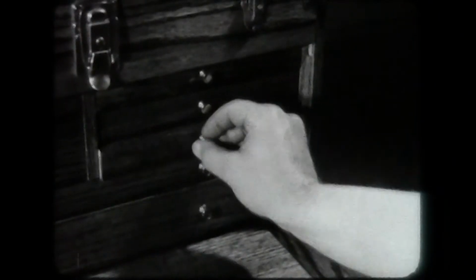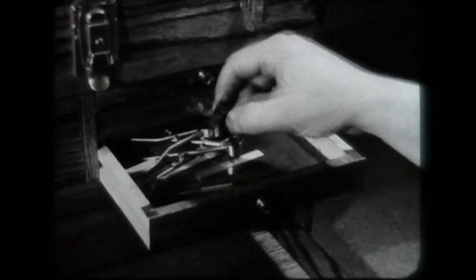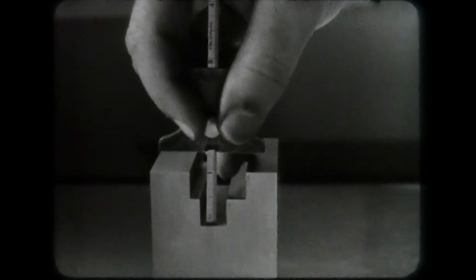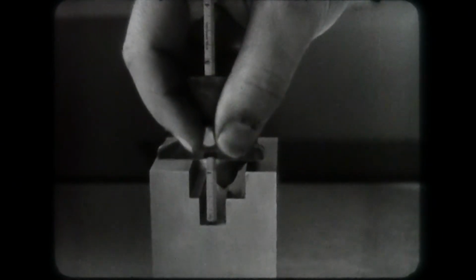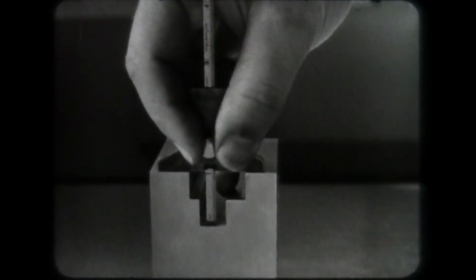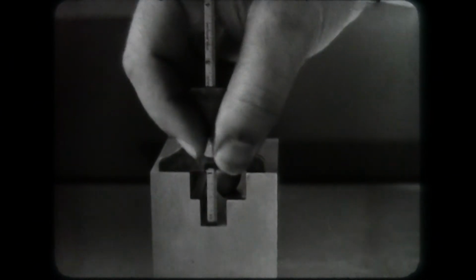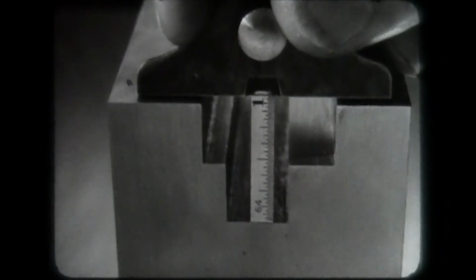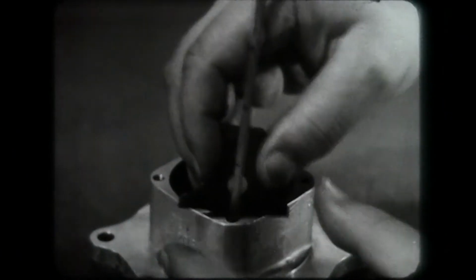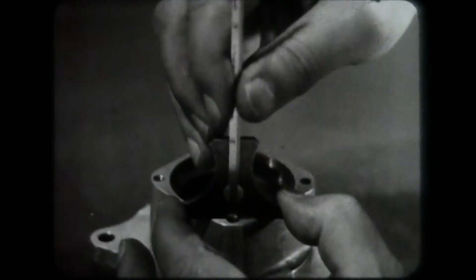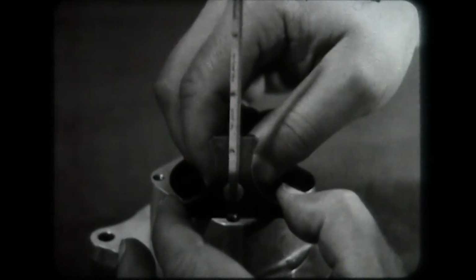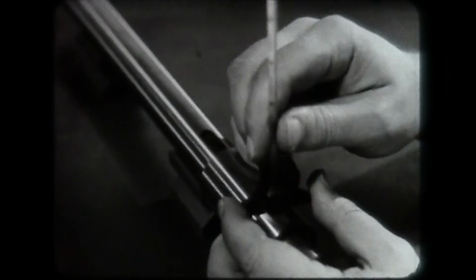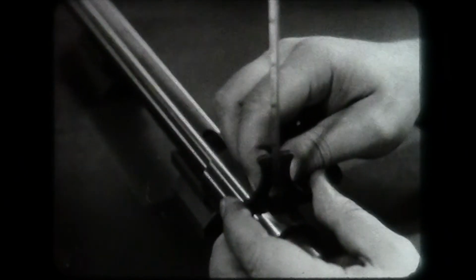One modification of the steel rule is in the form of a depth gauge useful for measuring slots and holes. Be sure the depth rule is held at right angles to the face of the work. Lock the clamping screw. The narrow rule will enter holes down to 3/16 of an inch in diameter. The rule depth gauge is convenient to use in measuring the depth of keyways.